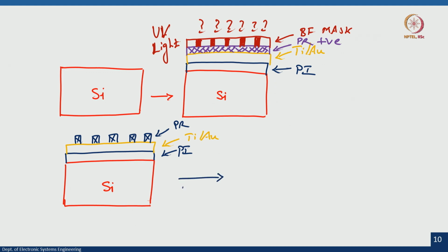See, TiAu: Ti is at the bottom, Au is on the top. First is titanium followed by gold, so first is Au etching. Dip this wafer in Au etchant, then DI rinse, deionized water rinse, then titanium etchant, and again DI rinse, followed by drying in nitrogen.